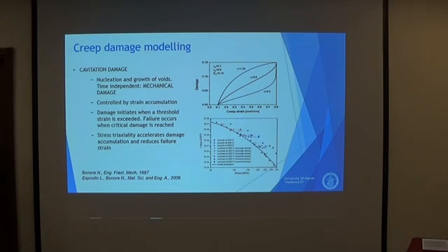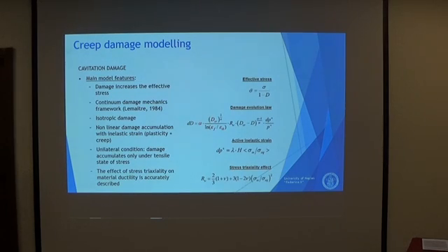For what concerns the failure, we use a cavitation model. It's a damage model derived from the continuum damage mechanics. It's a time-independent formulation. The purely mechanical damage is controlled by strain accumulation. Damage initiates when a threshold strain is exceeded. Failure occurs when the critical damage is reached. And the model we use is sensitive to the stress triaxiality.